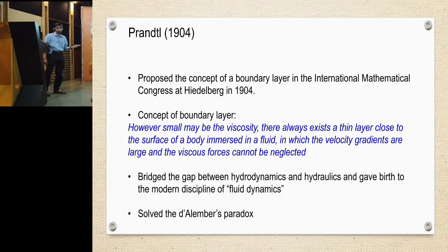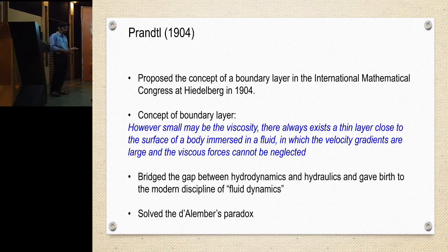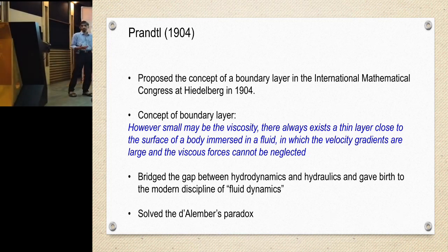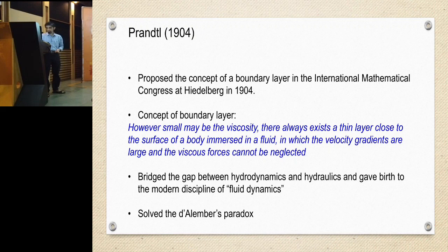It also solved d'Alembert's paradox, because in that thin layer surrounding the boundary, the viscous effects are important. So that accounts for the presence of drag on the boundary. The paradox, which said that vanishingly small viscosity results in finite drag, was resolved with this concept.